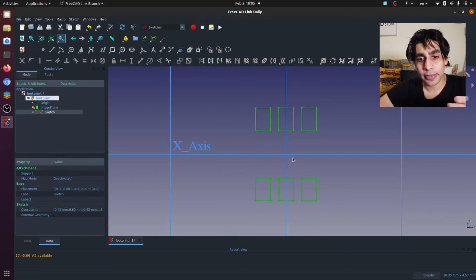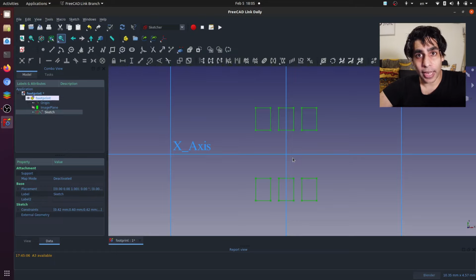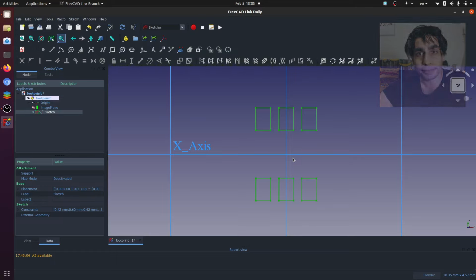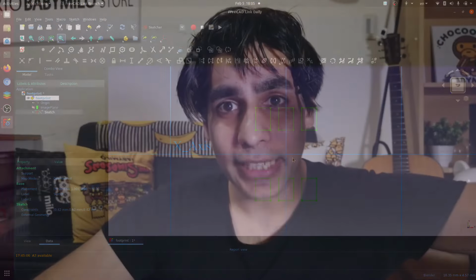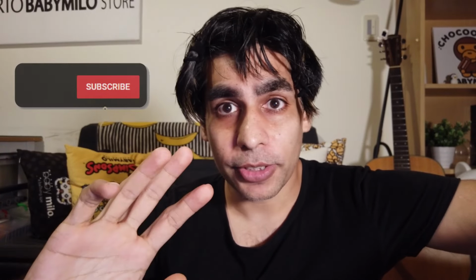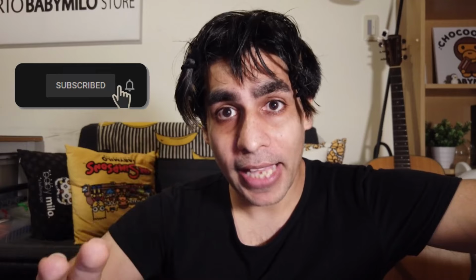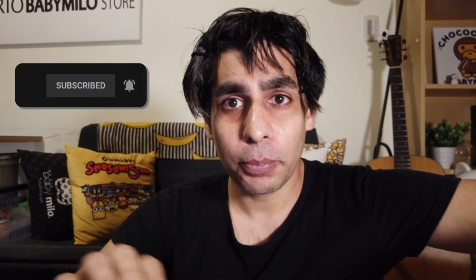If you were to take this image and export it as, say, a DXF into KiCAD, we'd have loads and loads of problems. The reason is that when you export a footprint, KiCAD doesn't know what a pad looks like or where the pad is located. So in order to get KiCAD to recognize that this image that we're seeing on the screen is an actual set of 6 pads, we have to put in additional markers into each of the individual pads to identify them.